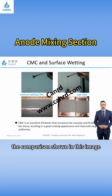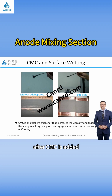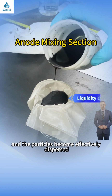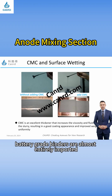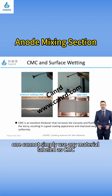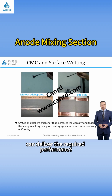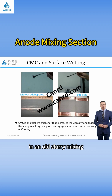The comparison shown in this image clearly demonstrates the impact of CMC on slurry behavior. After CMC is added, the slurry exhibits improved flowability and the particles become effectively dispersed, resulting in a dramatic difference in the coating outcome. It is important to highlight that battery-grade binders are almost entirely imported and are subject to stringent performance requirements. One cannot simply use any material labeled as CMC. Although many variants of CMC exist, only specific grades formulated for battery applications can deliver the required performance. Therefore, CMC plays a critical and widely adopted role in anode slurry mixing.